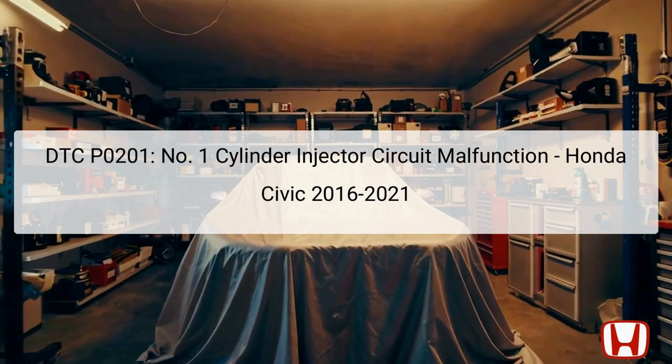The first step in the troubleshooting process is to verify the problem, which includes turning the vehicle on and possibly clearing the DTC to monitor any changes. Be aware also that other related codes, such as P0560, P068A, or P068B, should be resolved first, if they are present, as they can complicate the diagnostics for P0201. Let's delve further into the specifics of this error and how to address it effectively.